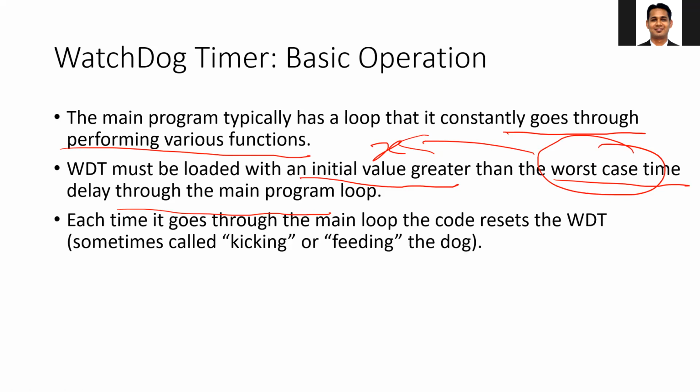Each time it goes through the main loop, the code resets the watchdog timer, say at the beginning or at the end, and this is called kicking or feeding the dog. The process of restarting the watchdog timer or counter is sometimes called kicking the dog. The appropriate visual metaphor for that is a man being attacked by a vicious dog. If he keeps kicking the dog,